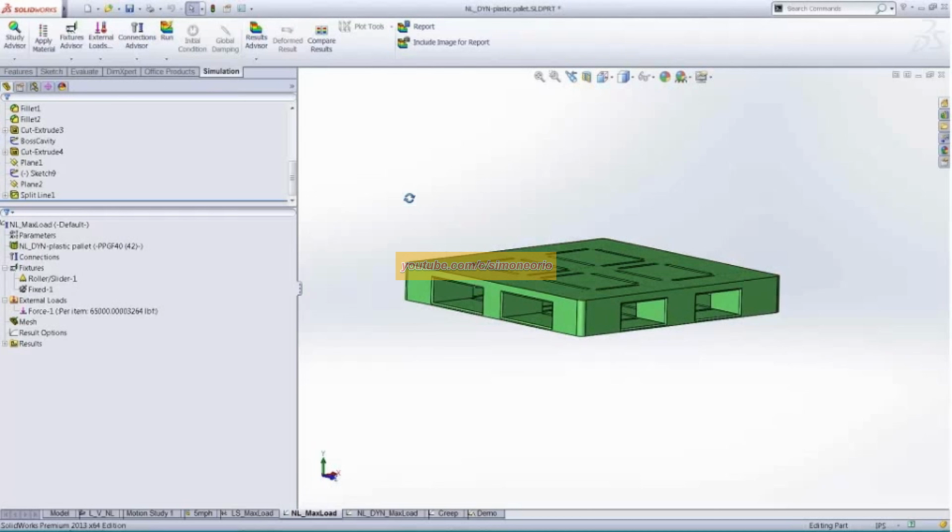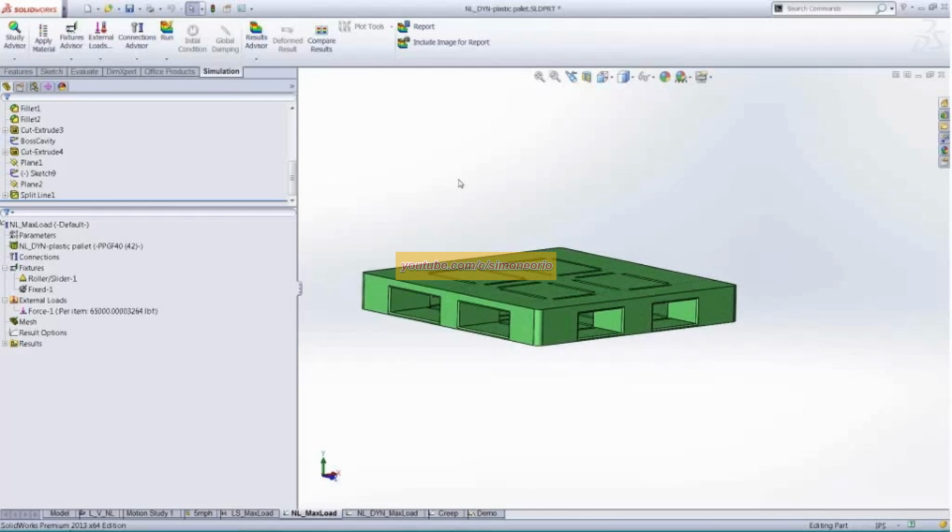And then, is a stress strain curve the only nonlinear property I need? If you're doing linear elastic or linear plasticity, that should take care of it. In order to do the creep, we do need to get the creep constants. As I said, one is an exponent on stresses, one is an exponent on time, and a little bit of Google searching around, and you can start digging up those constants, and/or talk with material suppliers. And you'll see here for elastomers, that's a very good segue.